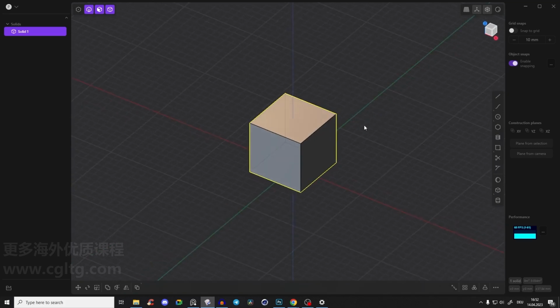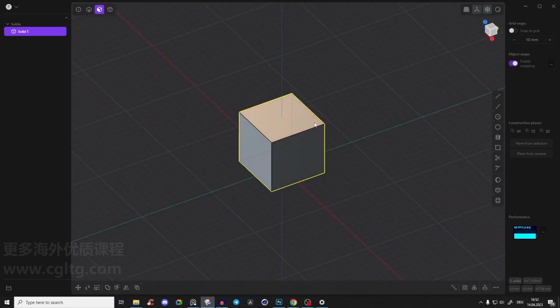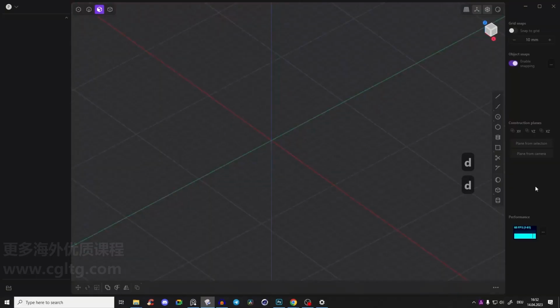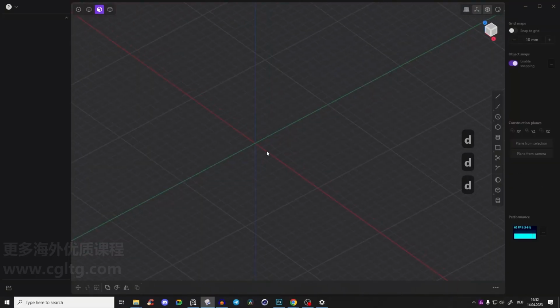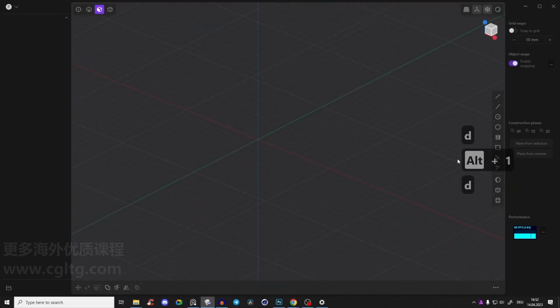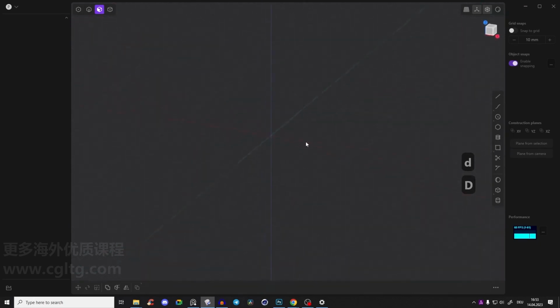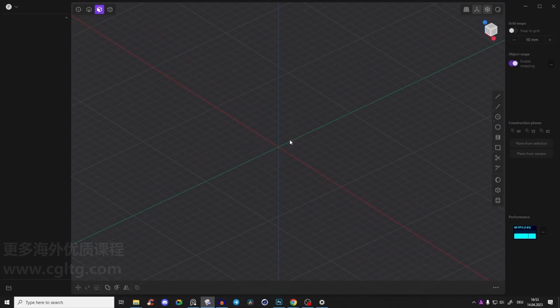So as we have this, you will start with the cube, and you can click on it, and then you will find a lot of different commands that you can use. But let's just delete it by pressing X or Delete. Oh, and I forgot to activate my overlay. So here on the right, you will see what buttons I am pressing. If you see a small D, it will be just D. If I press Shift D, it will show you a big D. I will talk over the shortcuts, but if I miss something, you mostly will see it here.